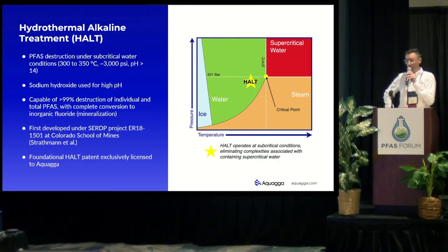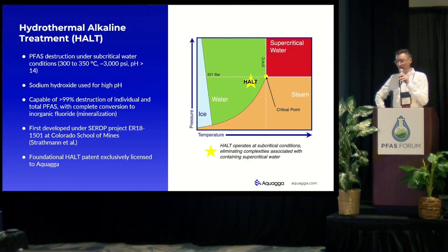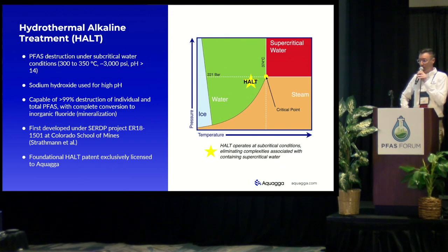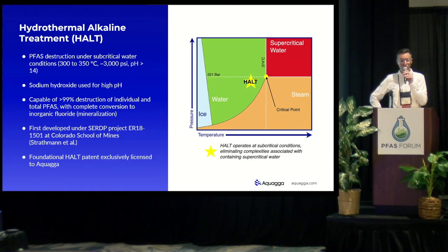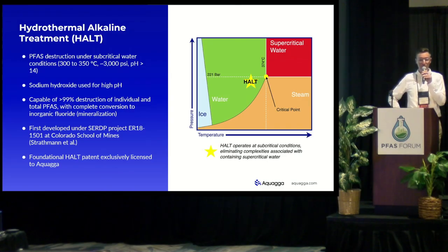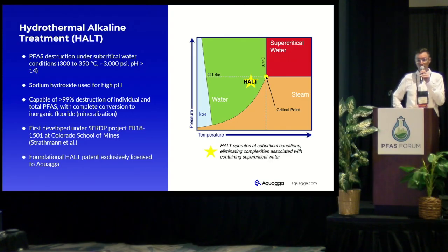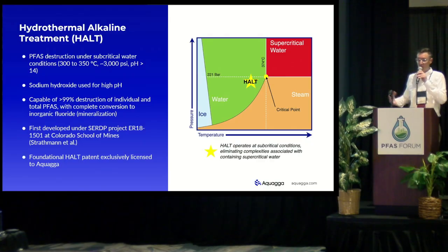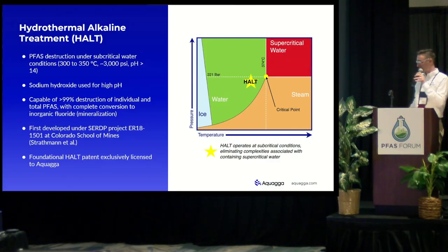The other constituents in the water are either sodium carbonate or other dissolved salts in the water, and then water. Those are the products. So after our process, we reduce the pH, we neutralize it, and prepare it either for safe disposal, discharge to the POTW, or ideally recirculation back to the top of the treatment works. And if you want more details on that plan, Emily's going to be discussing that during the case study.